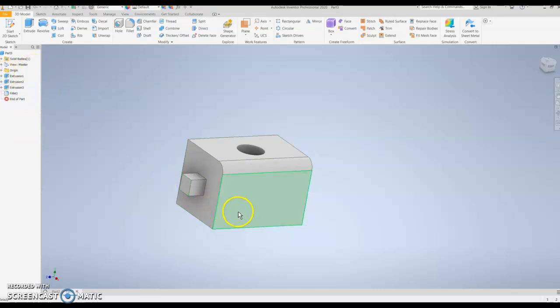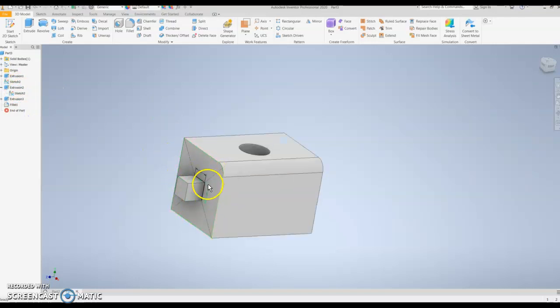You're going to find as well that once you've used up a sketch into a feature, your sketch disappears on your model. You can bring that back as well, though, if, for example, you need it for something. Let's say we're looking at this Sketch 2 here and we want to bring it back. We can right-click on that and click on Share Sketch. Now what we've done is brought that sketch back because we might need it for something else we want to do in that area, and it was important information.